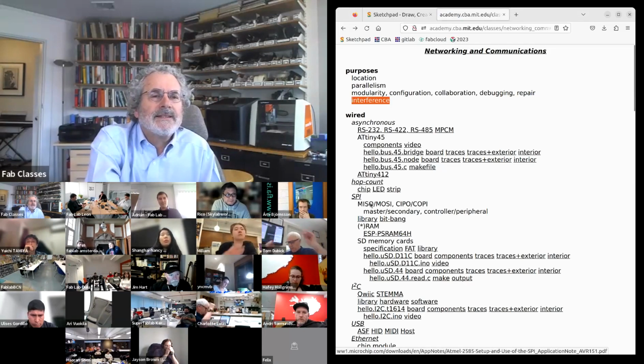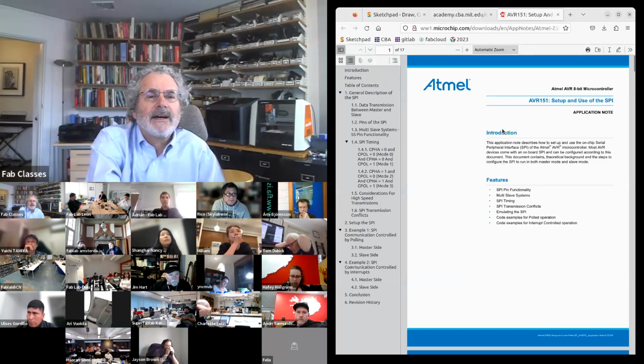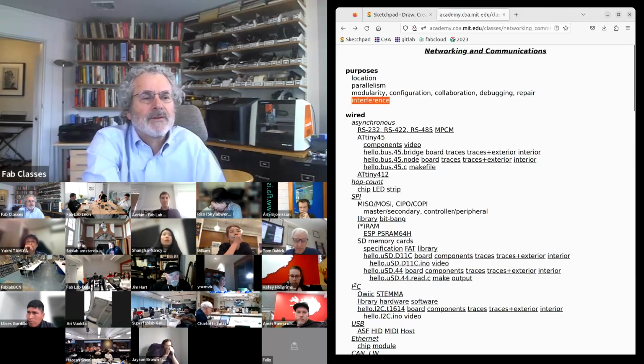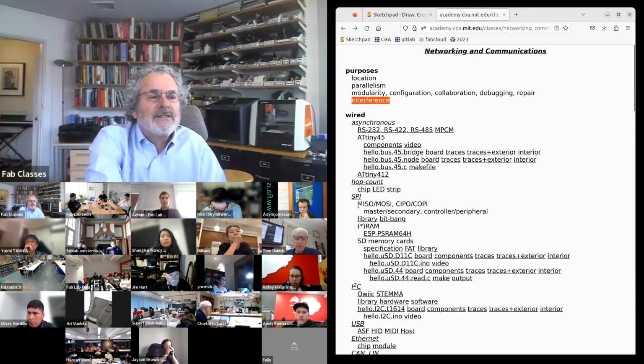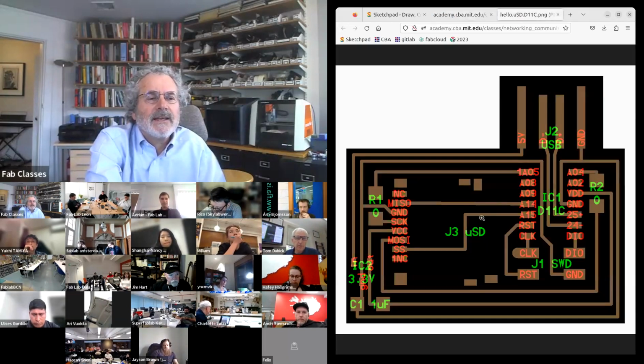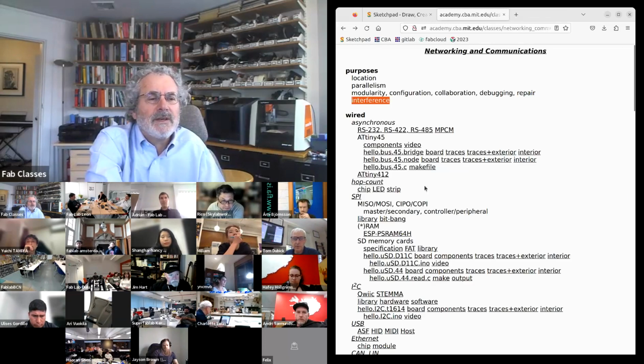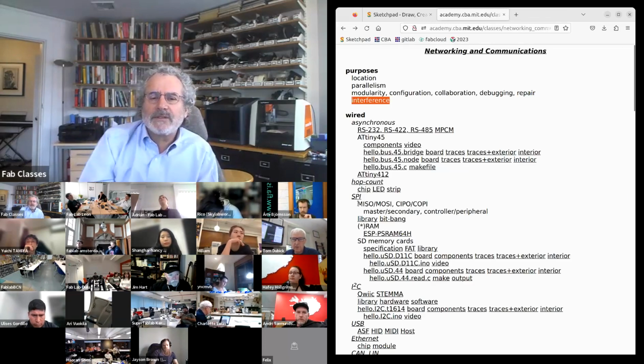The next one is SPI, serial peripheral interface. Historically, we're going to do this on SPI. There are two pins called MISO and MOSI. Historically, that was master in, slave out, master out, slave in.